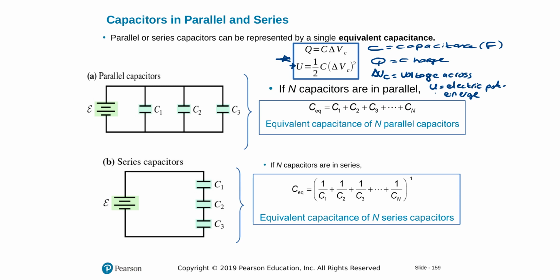We'll use this version of U. There are other versions, but we can always replace the known values by unknown and resolve. So I'll give you one version of it. One important thing to keep in mind is that adding capacitors and finding the equivalent capacitance in series and parallel circuits is exactly opposite to how resistances work.